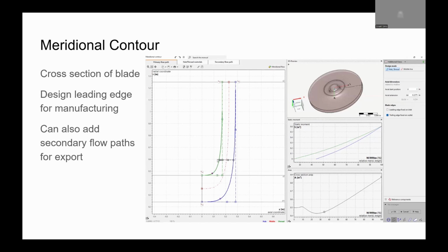And oftentimes this black line will have curves added to it, and that impacts our manufacturability because if we have a weird looking edge to our blade with overhangs and stuff, then it's much harder to manufacture. I mean, we can still 3D print it probably, but I change it to always be sort of vertical to aid in the manufacturing process and make sure that whatever happens with the 3D printing, we can still get the impellers done.